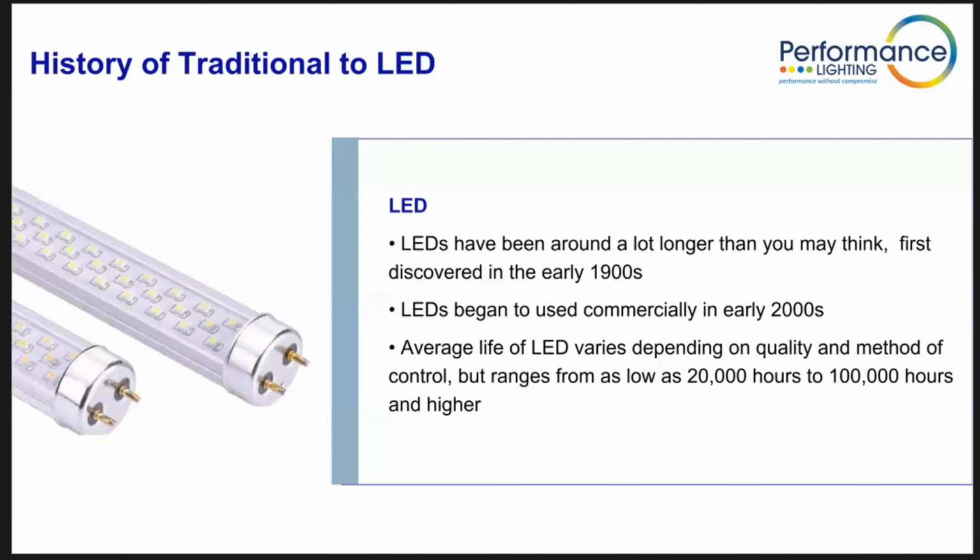LEDs need a compatible LED driver to control and operate them. Quite a bit more specific than the old fluorescent, because the fluorescent was very generic. A 5-foot 58 watt was a 5-foot 58 watt, and there were no differences other than colour temperature. We'll talk temperature a little bit later. But it was very much, you had a 5-foot 58 watt tube, you had a 5-foot 58 watt ballast.